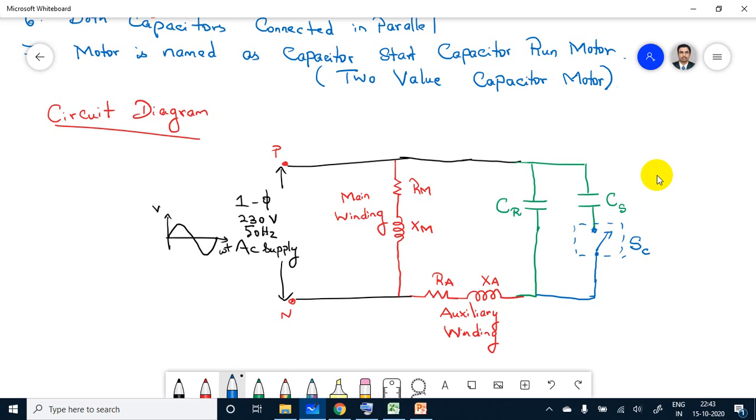This is the centrifugal switch. And inside your machine, there will be a rotor structure. This is the rotor, which has slots, almost 36 slots or 25 slots. Since it is a squirrel cage rotor, the rotor bars are short circuited with the end rings, but in slip rings, the slip rings are short circuited with brushes in series arrangement with external resistance. The single phase induction motor has only the squirrel cage rotor.